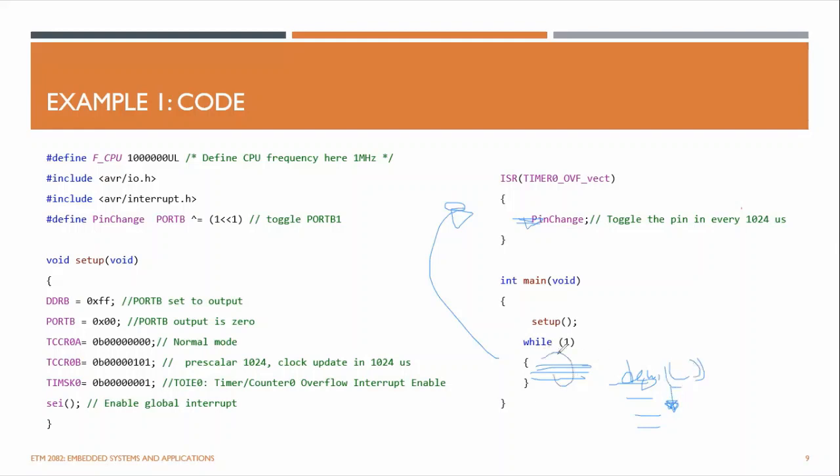But here you can do any other work, and only when an interrupt is generated do you go there and do this work. So it is more beneficial to use timers without using these delay functions if you want to generate some time windows.